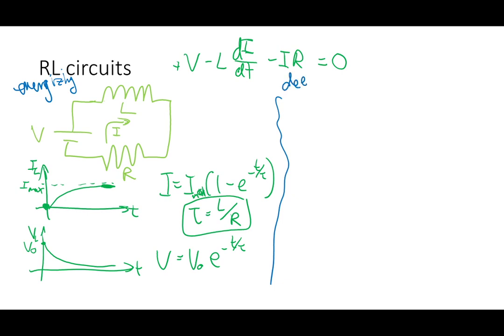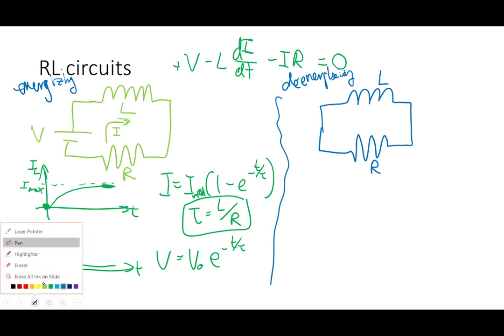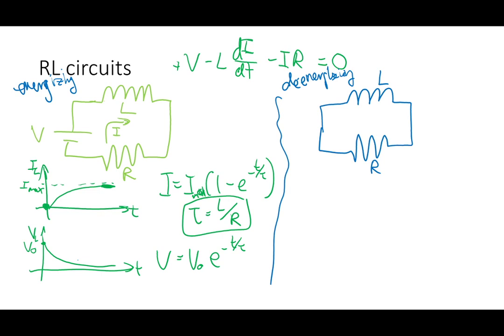So if you're de-energizing, then you're just left with an inductor and a resistor. And what's not drawn on this picture, or I guess I'll make it a little more explicit, is that at the moment you disconnect the battery, there is still some current going through that inductor, which is the current that it is going to maintain for a split second of time.